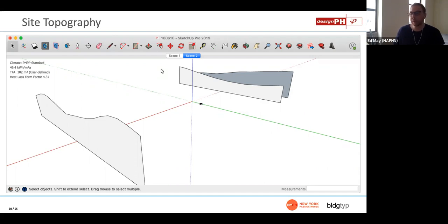The number of polygons matters quite a bit when it comes to speed of shading calculation. So the number of polygons, you want to keep that as low as possible. Here, the number of polygons is 3, right? As opposed to the topography, where the number of polygons could be thousands and thousands. And yet they describe basically the same shading condition. So, you can do it either way. This is my recommendation. This is how we do it in a lot of our projects when we have context like this, where we need to drop in some large elements.